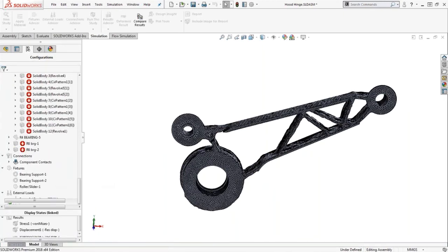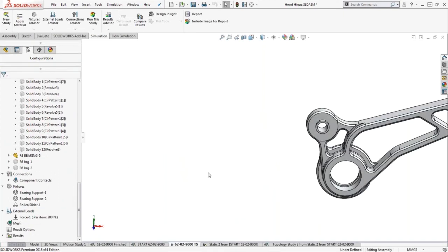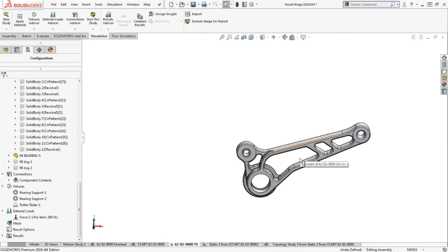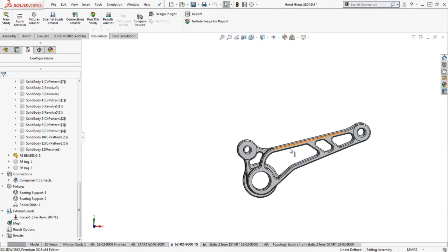All right, so if I activate this configuration within the same model, essentially what we did was recreate, or actually add, those features to the original workspace and say, well, the topology optimization told me to cut out these pockets here, potentially some areas in this area as well, and this could be my overall shape. So you're using it as a reference for you to redesign the original model to get something like this.